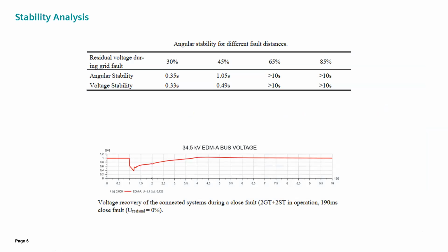The main purpose of our decoupling system is to ensure the power stability, as I described before. We can see a graphic here showing why we need to be fast for critical cases. In the graphic, the stability is changing rapidly within a couple hundred milliseconds. For example, while working in grid-connected mode, the stability issues depend on the turbine generators' set inertia, as well as their controller performance. Angular stability defines the maximum fault duration which the generator can withstand without having a pole slip. This is mainly driven by inertial system response.